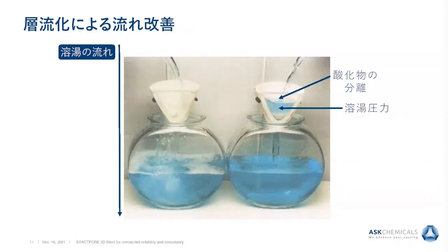When analyzing or reviewing laminar flow improvement of molten metal through filters, one can use water modeling. Before simulation software was available, many steel foundries used water modeling to simulate any issues with turbulence or reoxidation in their runner systems or casting cavity. The kinematic viscosity of water is very similar to many ferrous alloys.